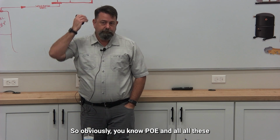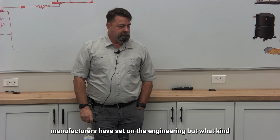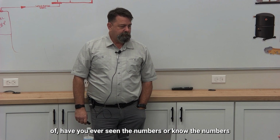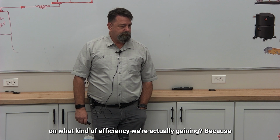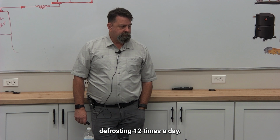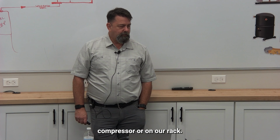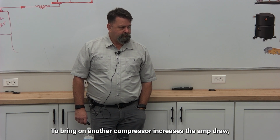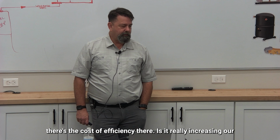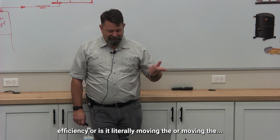Anybody have any questions about my evaporator coil fins per inch? So obviously, DOE and all the engineers for all these manufacturers, et cetera, on the engineering. But have you ever seen the numbers or know the numbers on what kind of efficiency we're actually gaining? Because in my feeble little brain, if we're turning the case off, defrosting 12 times a day, and then turning it back on, we're increasing the load on our compressor or on our rack. To bring on another compressor increases amp draw, there's the cost of efficiency there. Is it really increasing our efficiency, or is it literally moving the shower?